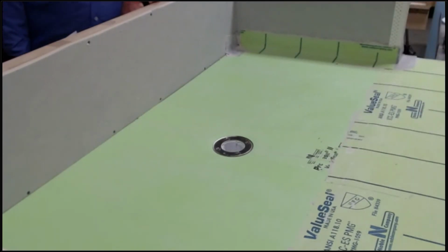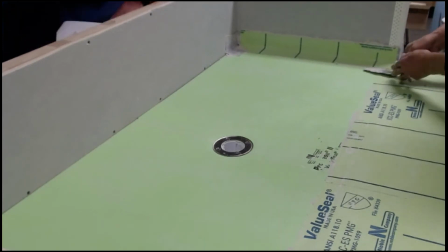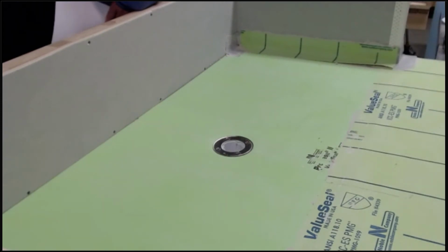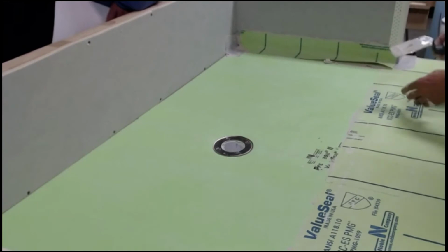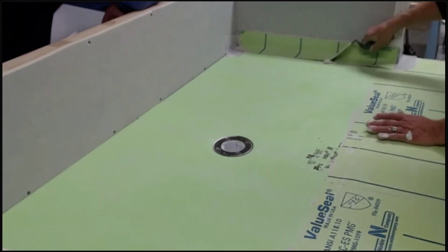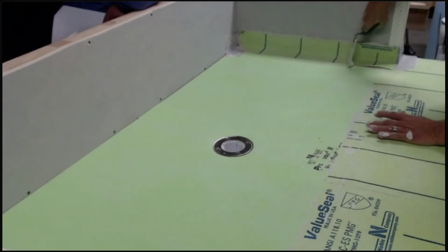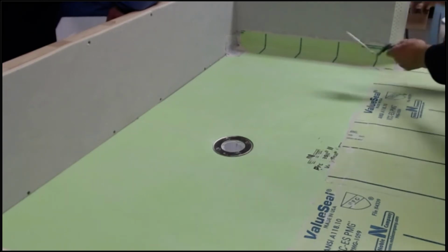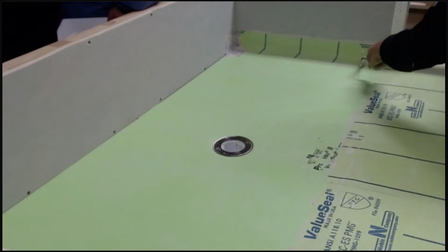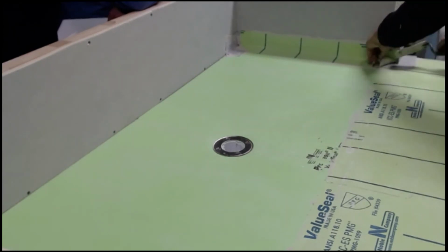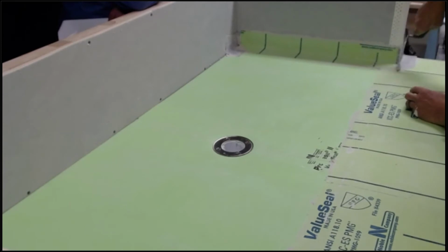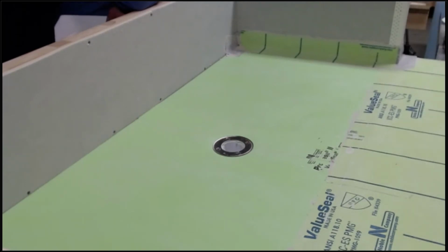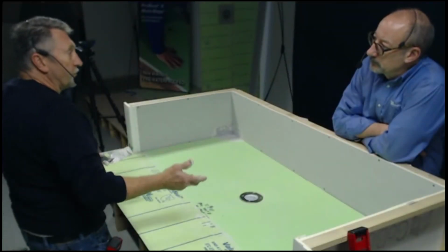And with the Value Seal, you can see the coverage on that. Just peel it back to look, and you can see a lot of coverage. Now I've got a spot there that maybe is a little light. Just simply apply some in. Throw some in there. Tool it in. You'll want to make sure at the end of your assembly that you check everything, make sure everything is tucked in tight, and you have plenty of coverage before it cures up. Say I'm a little bit thin out here, I'd put a little bit there and tool it in. Once you've got the assembly done, you let it sit overnight, and you're ready for a flood test.